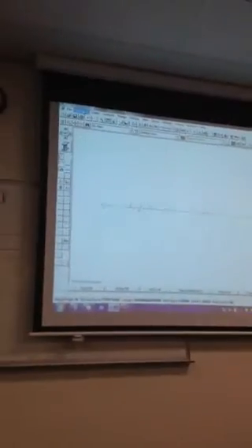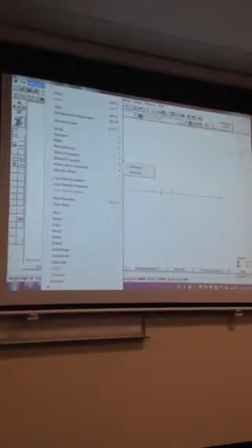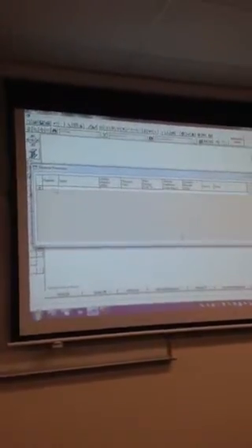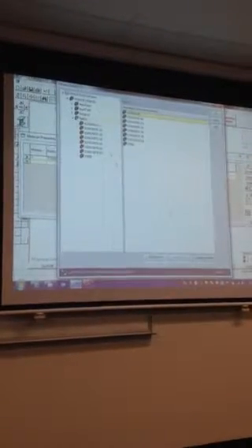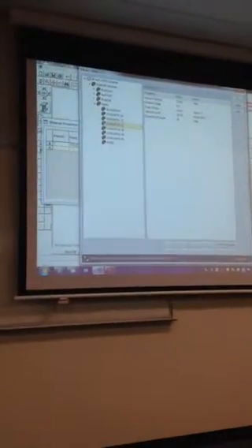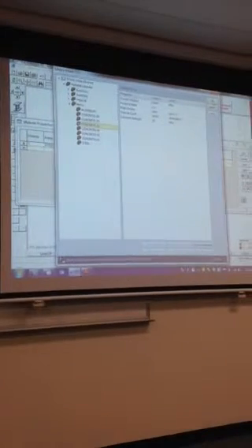So we've got geometry and we've got our section properties in. The next thing we need to look at is material properties. All of the slabs and all the beams are going to be 32 MPa, so we're going to call it material number 1. It defaults to steel, but it's got a library for us, so we're just going to go down to concrete 32.